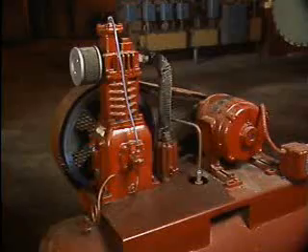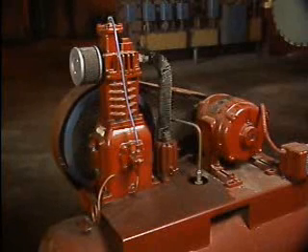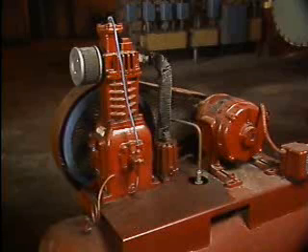To keep the pressure from rising uncontrollably, some method of regulating the pressure must be used to control the amount of gas that is delivered by the compressor. Pressure regulating methods range from a simple on-off system to more sophisticated methods, such as the use of inlet valve unloaders. When pressure is regulated by a simple on-off system, a sensor in the receiver controls the compressor's drive mechanism.